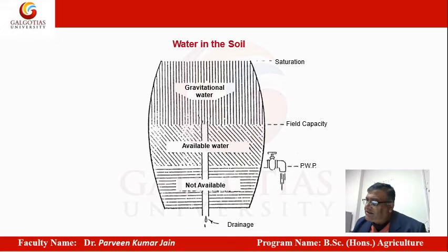What is happening is that you're pumping out water from the ground, and then you're waiting idly for this water to disappear, so that it may go in runoff, leaching, or infiltration. And then the main condition is reached, technically, when the water in your macro pores goes, and only air comes into these macro pores, but the micro pores have water.